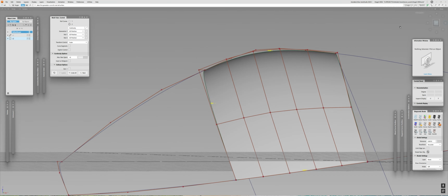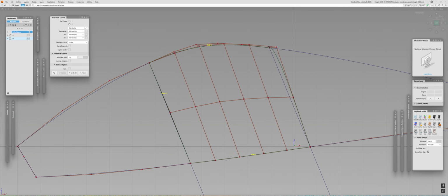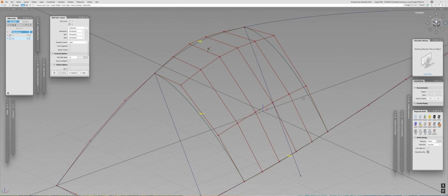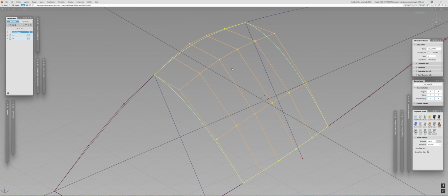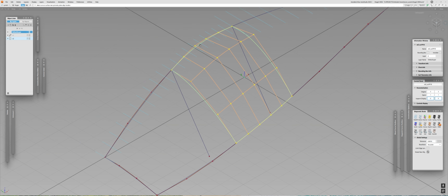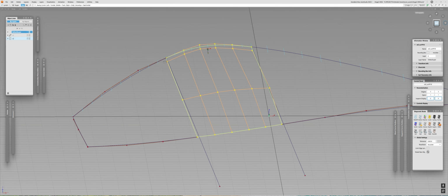It's skewed, so it doesn't really follow the edge I'm looking for, right? Let me show you. Here is the line, it's how it's bulging, and yeah, it's just not great. So what we're going to do is repeat the same steps, as I said. So activate the symmetry plane align, select our surface, delete the history for the rail, and here we go.